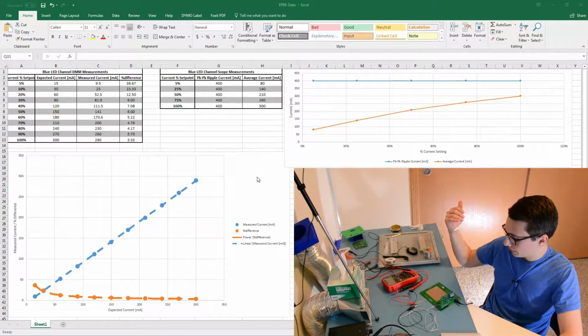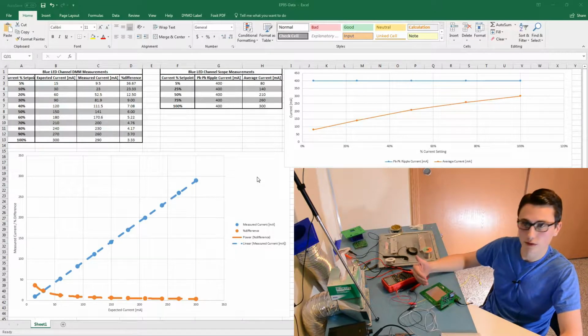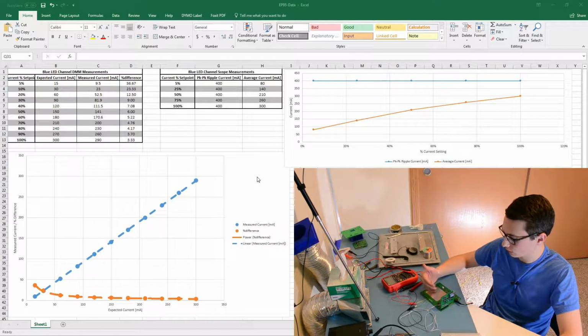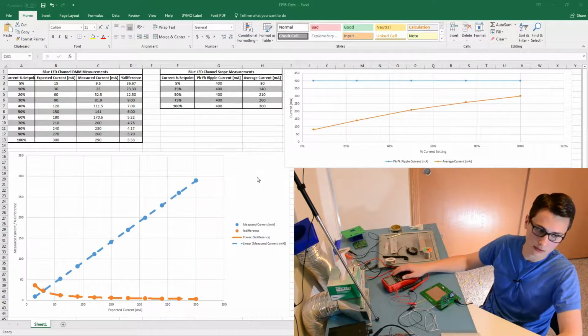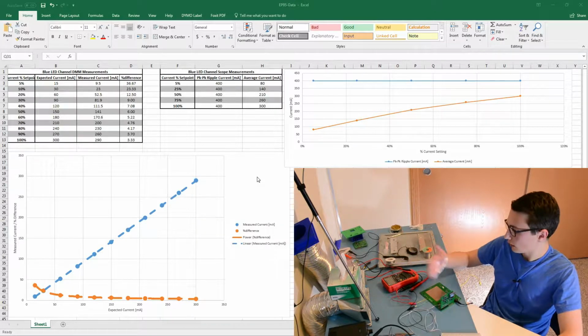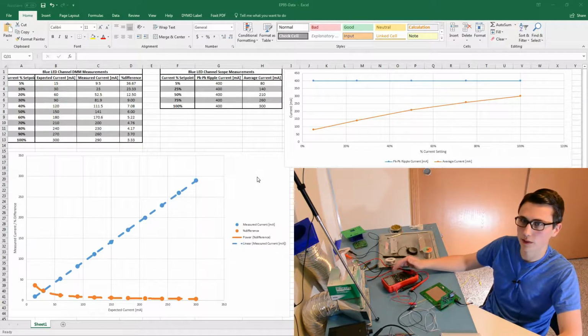So that is the switch mode power supply tolerance, the current shunt tolerance, the tolerance on the timing of the PWM out of the microcontroller, along with the action of the BJTs that are actually disabling the switch mode power supplies. The PWM was still a factor because that was about 90%. So all those tolerances stacked up ended up being around 3% different.